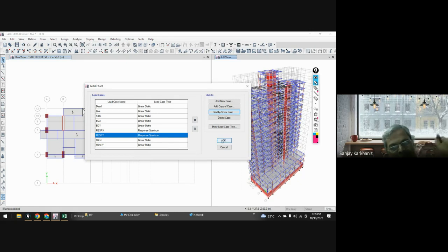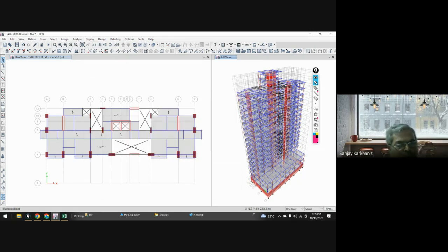So now this is the first step that you have to do. Here we have scaled up all response quantities of dynamic base shear with that static base shear. We have gone through that PPT where I have given you in detail why it is to be scaled up. Because in one case we are finding VB with the help of earthquake character, and in another case, that is dynamic, we are finding VB based on actual distribution at every floor level.